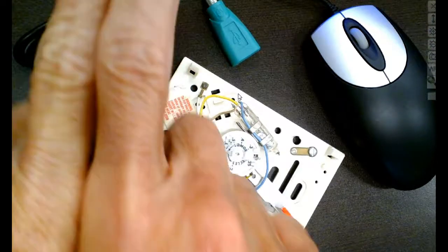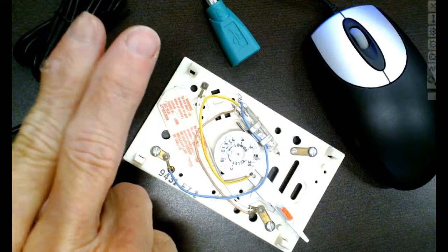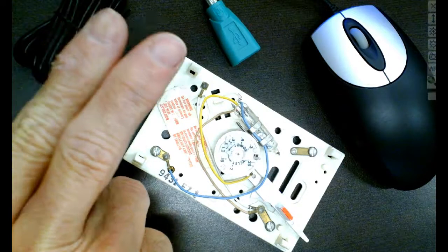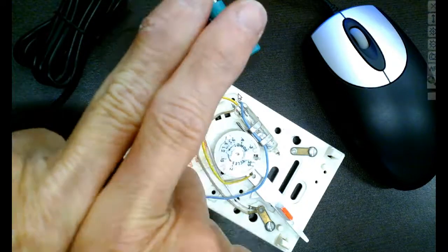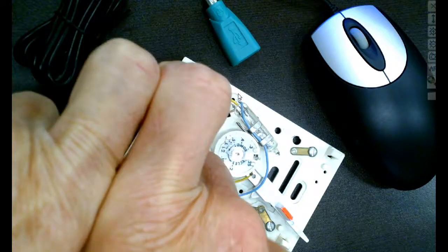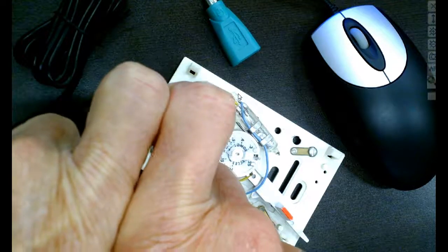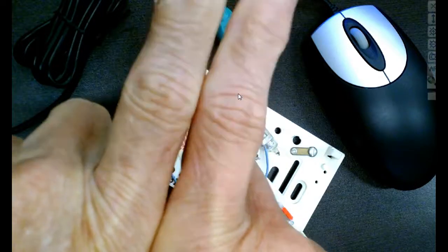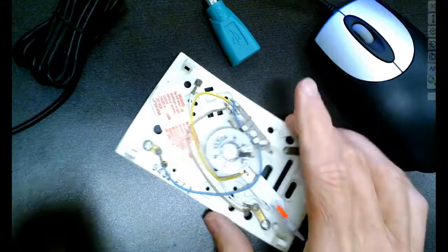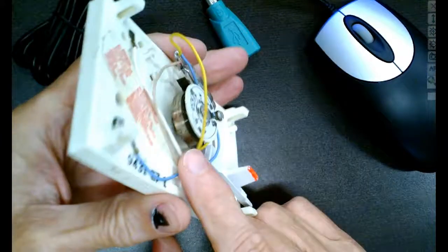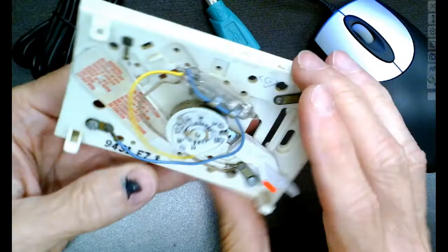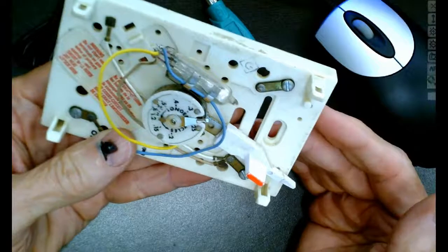But if you put these things together, then one of them is going to expand faster. They usually put that on one side, and what does it do? It literally bends. Well, it's already bent, then it has a tendency to spread out. So that's all this is right here. This is a bimetallic strip, and this used to be a thermostat. This is the way thermostats work.